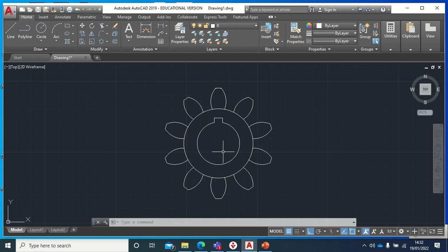Okay, so what you have to do is select everything and type, what is it called? Explode. We should have checked the associative or so there. But mine was already checked. So select everything. You done it, yeah? Yeah. Okay, cool. So once you got that one, now if you take your cursor, it takes just one, isn't it? Yeah. It takes just a tooth.